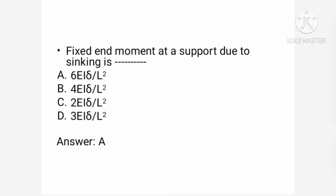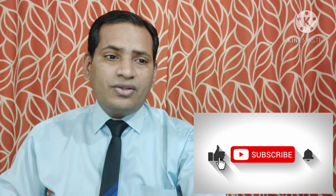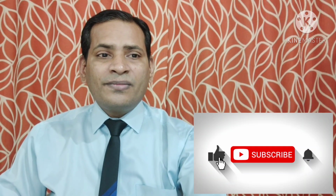Next question: fixed end moment at a support due to sinking is 6EI delta by L square. Okay, so option A is correct. It can be negative or positive, so only the determinant is asked. So the fixed end moment value will be 6EI delta by L square.